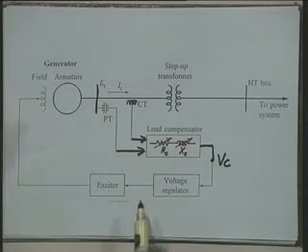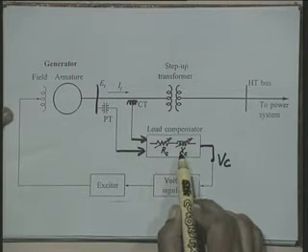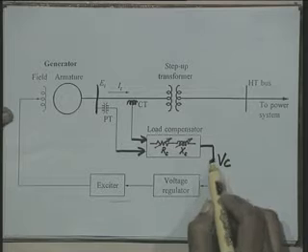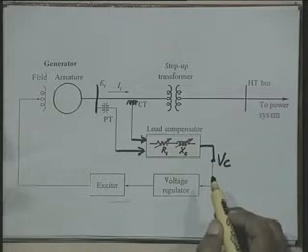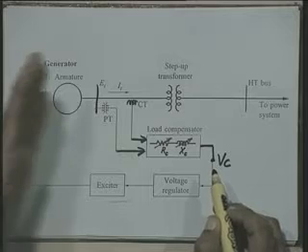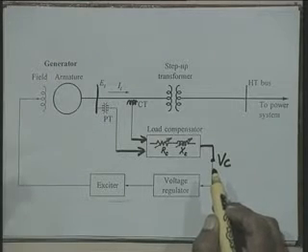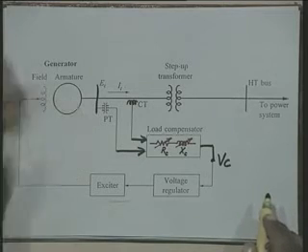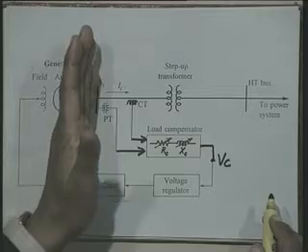Now, suppose I take Rc and Xc positive. Then the voltage which we regulate is not the terminal voltage, but a voltage somewhere inside the synchronous generator, because there is some generated voltage inside the synchronous generator, that voltage drops and we get a terminal voltage here.